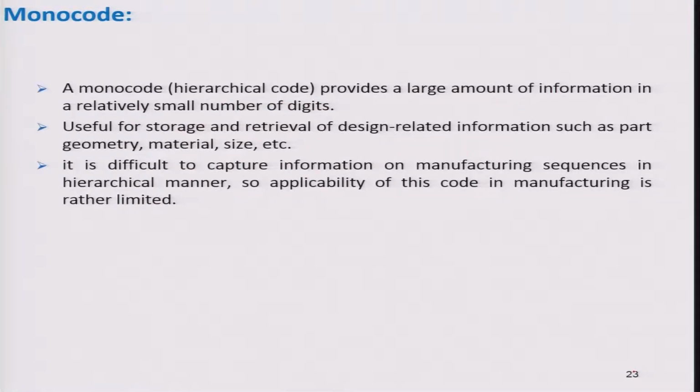It provides a large amount of information in a relatively small number of digits, and is useful for storage and retrieval of design related information such as part geometry, material size, etc. But it is very difficult to capture information on manufacturing sequence because it is hierarchical. So the applicability of this code in manufacturing is rather limited.